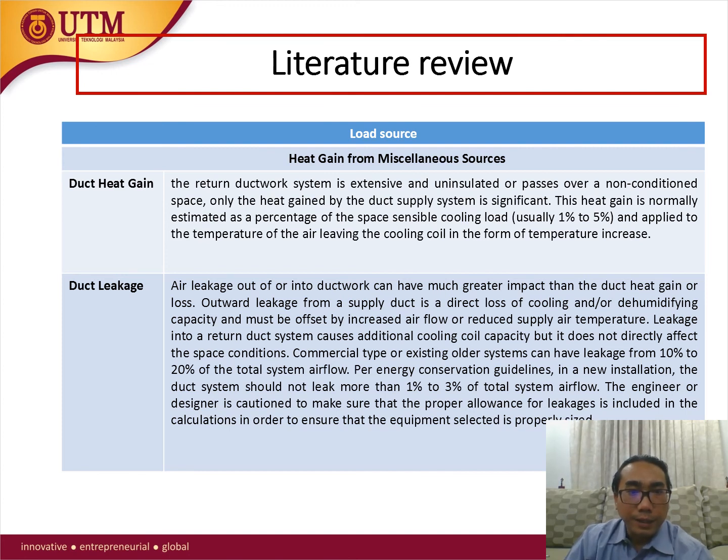Duct heat gain. If the return ductwork system is extensive and not insulated, or passes over a non-conditioned space, only the heat gain by the supply duct system is significant. The heat gain is normally estimated as a percentage of the space sensible cooling load, usually 1% to 5%, and applied to the temperature of the air leaving the cooling coil in the form of temperature increase.